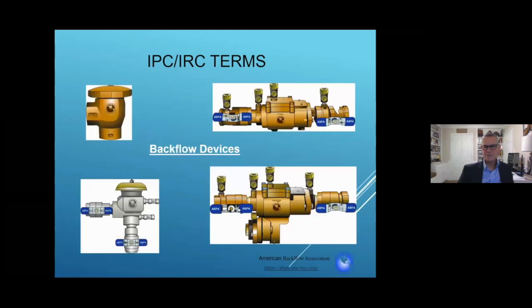You don't have the luxury of that in a lot of cases. Most tanks have direct connections. And when you have a direct connection of a supply pipe, you're going to need some type of backflow protection. So I put some pictures in here. There's a number of different types of devices. Some look very similar. The two devices on the right look very similar. They're not. There's a big difference.